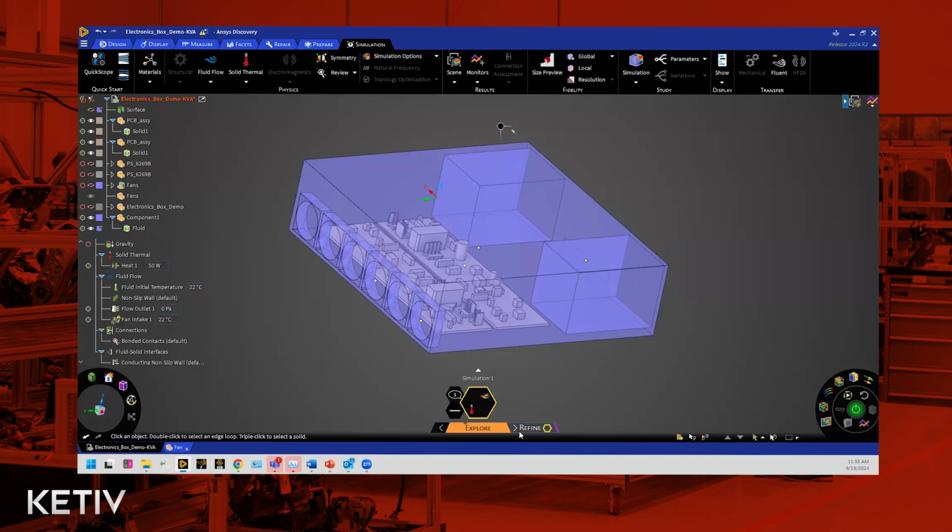You can use under the hood solvers like Ansys Fluent and Ansys Mechanical to run the same simulation, but you could also use something called the Live GX solver inside Ansys Discovery itself in the refine mode to both leverage GPUs or CPUs to get a solution.